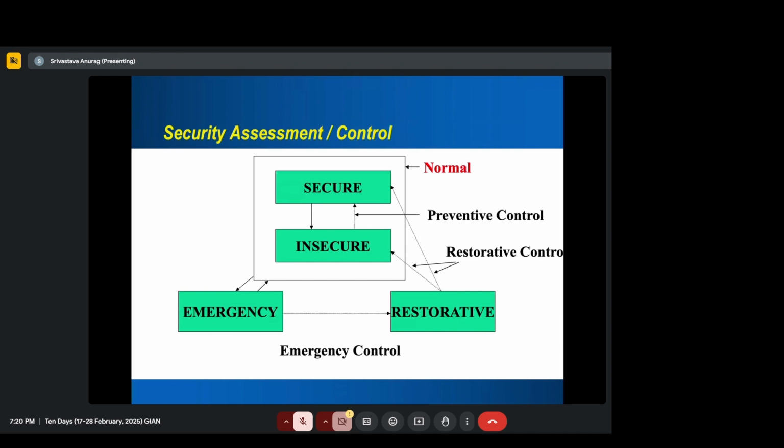So not every utility runs the stability, because stability is voltage stability, frequency stability, and transient stability, right? Not everyone runs all of these due to the computational burden that will take, plus being preventive requires you to be more accurate, and being accurate in transient is more tricky compared to being accurate in a steady state analysis.